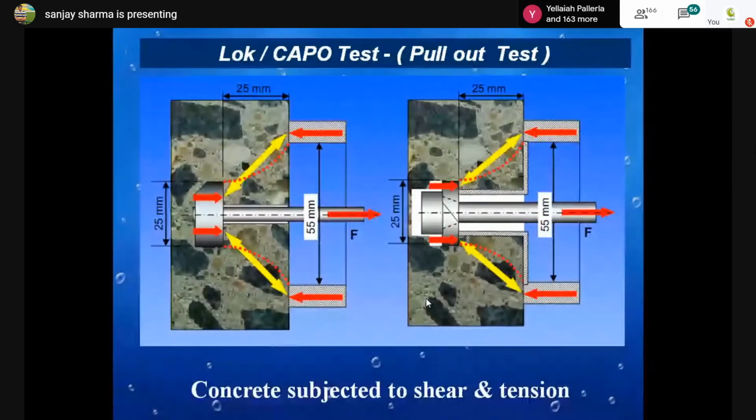It is again a very commonly used test. Basically, you can find out that this is the cone of failure, this is the embedded part in the concrete, and the pull-out test is a very accurate test. In accuracy, it is almost comparable with your core test. Even core is sometimes not very reliable because core is taken at the site. Sometimes you do not prepare it. We will come to that later, so why discuss it here.